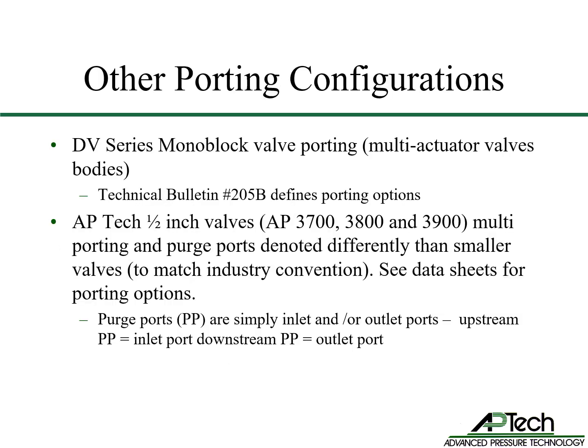APTech also offers the DV series of monoblock valves with configurable porting options. See Technical Bulletin number 205B on our website for more information. APTech's half-inch valves have different porting configurations, including purge ports. Purge ports are an inlet or an outlet port either upstream of the seat or downstream of the seat. See the AP37 datasheet for port configuration options.